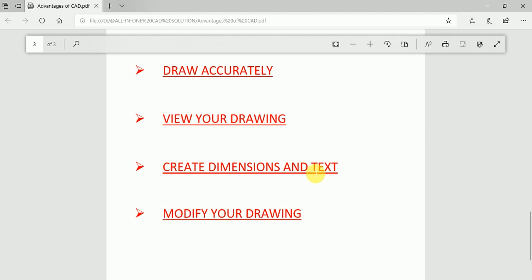Okay, with AutoCAD, you can create associative dimensions and tags on the layout in paper space. Associative dimensions are tied to the underlying model. Changes to the model automatically update the dimension value. If we annotate something, then the whole drawing changes automatically. Standard dimension types include linear dimension, radial dimension, ordinate, angular, baseline, and many more. You can easily revise the content, font, size, spacing of the lines, and rotation of the text.